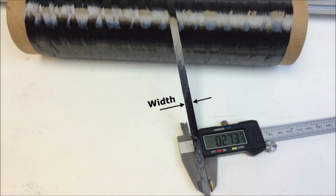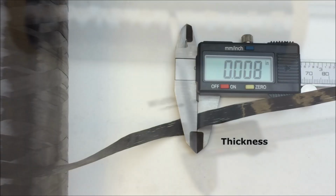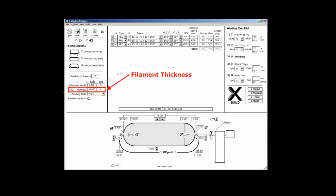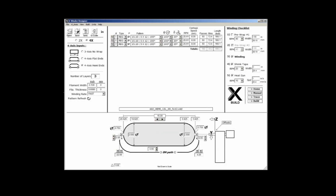Filament width and thickness. For the filament width and thickness, measure the bandwidth and the thickness and input to the designer software. Delivery head path adjustment. Delivery head path adjustments are critical to a well-tailored winding, and there are several inputs to fine-tune the delivery head path to get it just right.